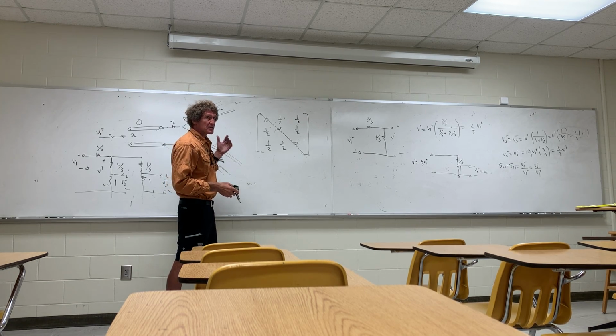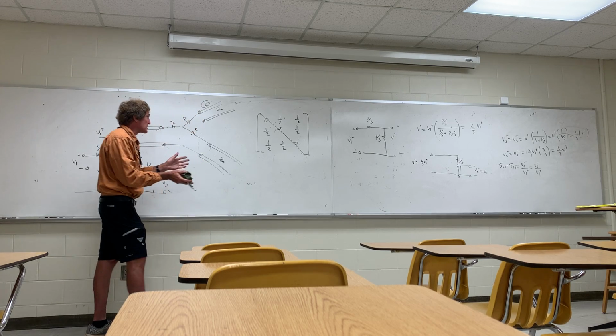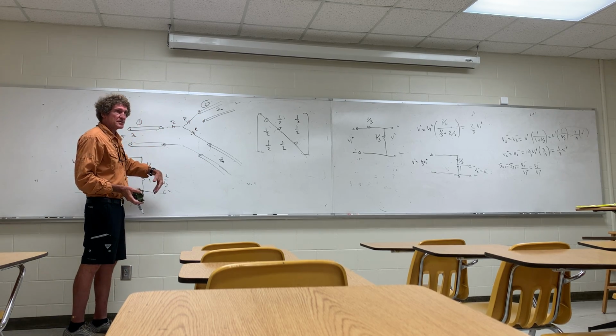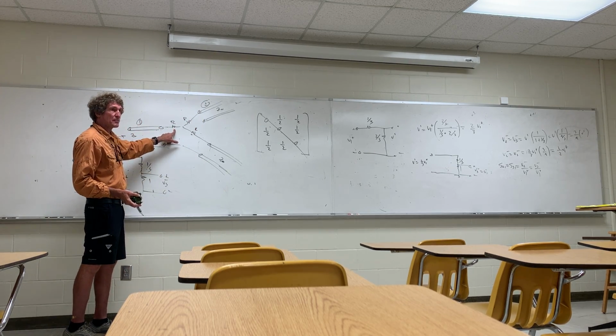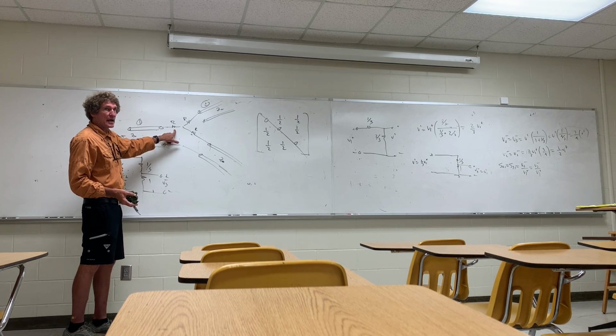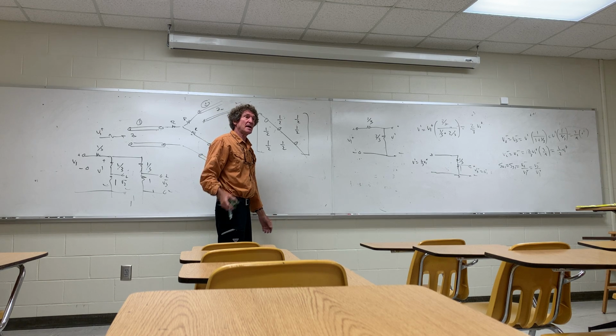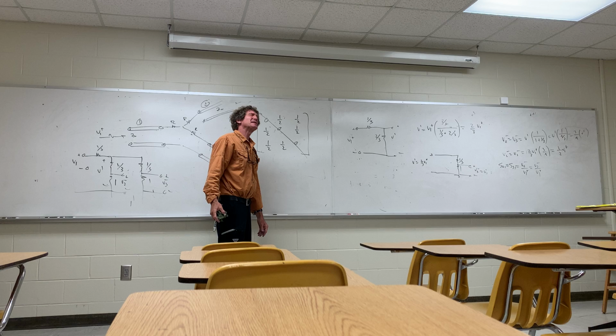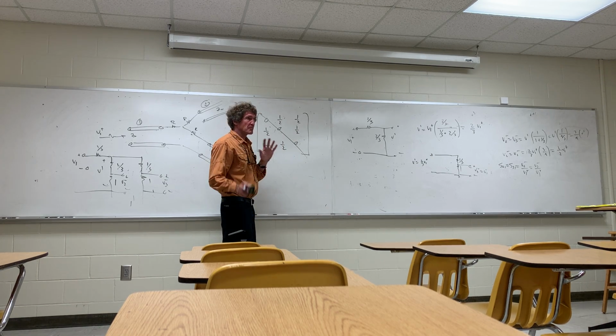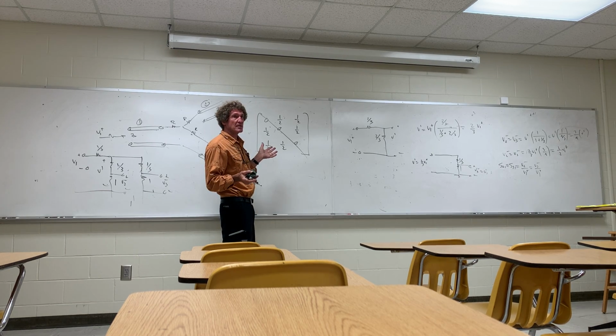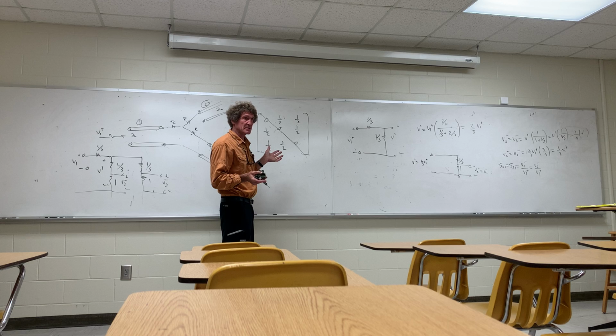If it didn't split 2 ways, if it split 3 ways, you'd have a different value for R here that you'd have to calculate. And again, all the diagonals would be 0 and everything else would be the same value. I think for a 3-way split, these all become 1/3, but honestly, I'm not sure. It would be a 4-port device and everything would be 1/3, I think, except the diagonals. But that's with resistive division.